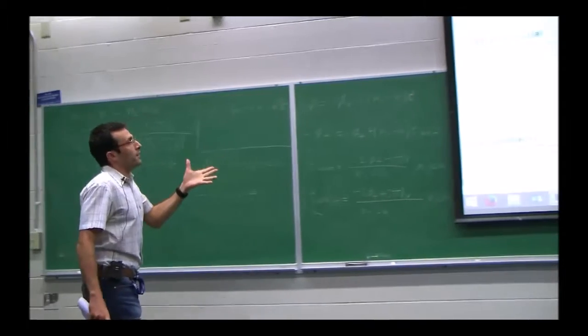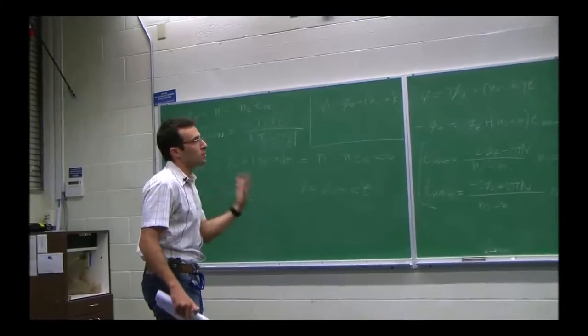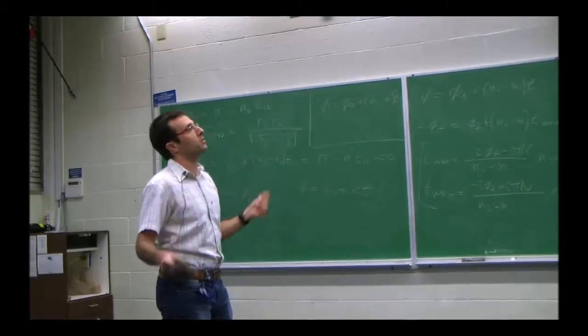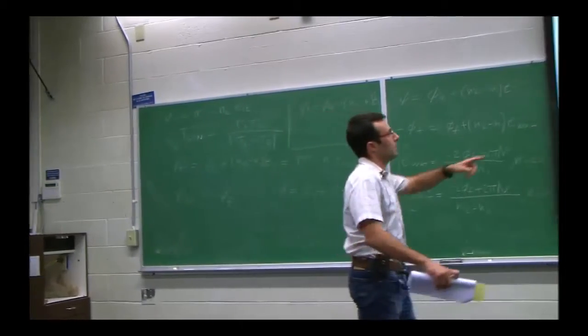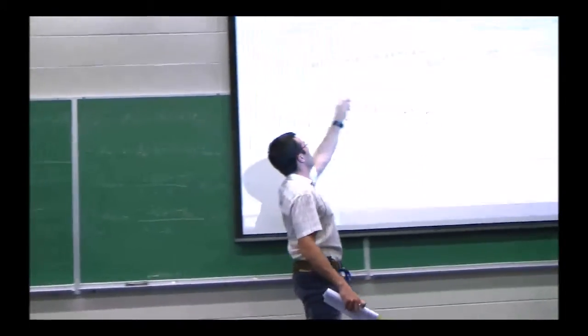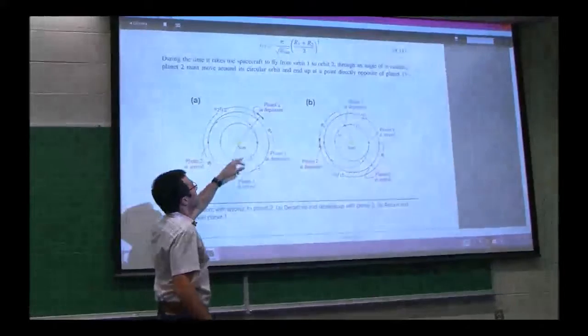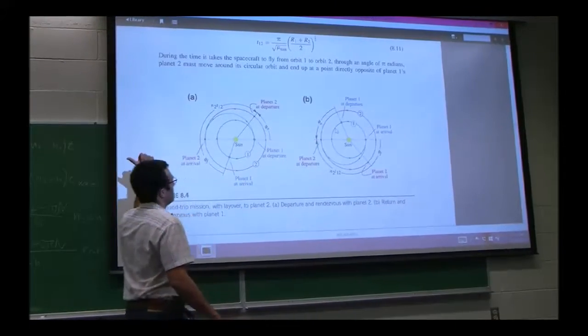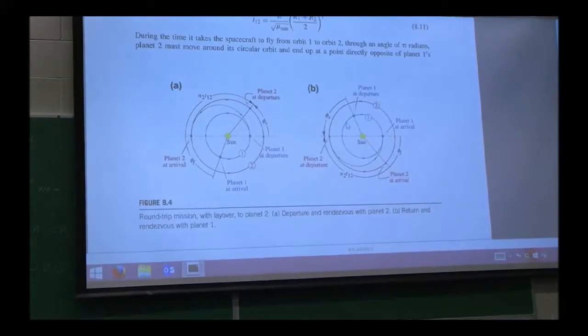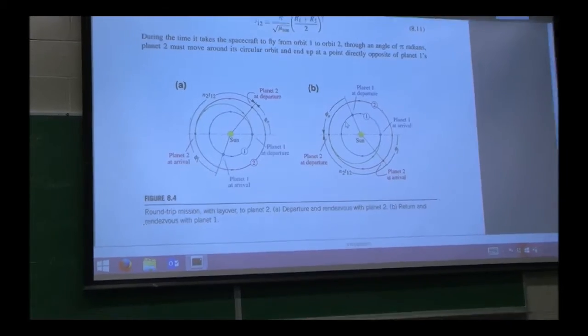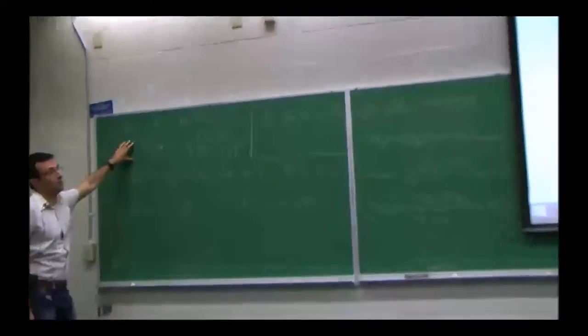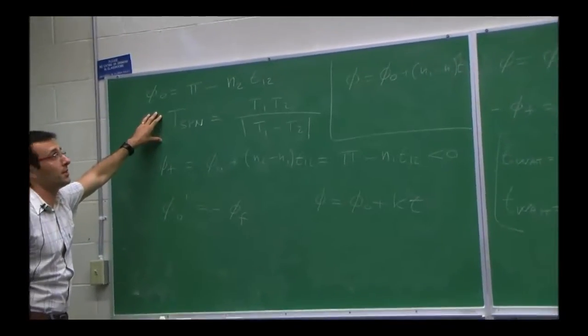So this should really cover the timing of these maneuvers. They are just Hohmann maneuvers from the sun's point of view. There's really nothing special about them. You leave a point on this circle, and you reach another point here. You just have to do it when this phi0 respects that condition, and right here. And this repeats itself every synodic period, which is a long one between Mars and Earth, as we've seen last time.